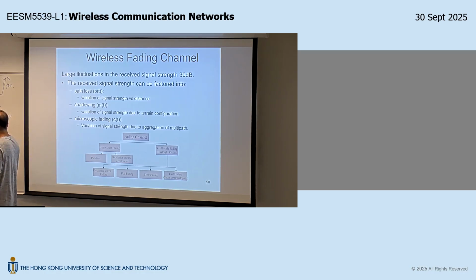So in a linear time varying system, the corresponding parameter that completely encapsulates the behavior of this black box is still an impulse response, but this impulse response becomes two-dimensional. It's time varying and depends on the delay. So the impulse response is now generalized to a two-dimensional function, put it this way, okay?